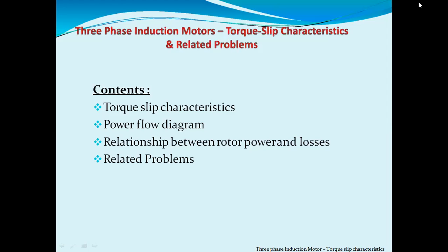So we can say torque will depend on the flux which interacts with the rotor of the three-phase induction motor. Because we have seen Faraday's law in the DC motor and in the AC motor, when we use the winding, the conductor is cut by the magnetic field, due to which there is induction. So torque depends on the rotor current and on the flux interacting with the armature, or the rotor.